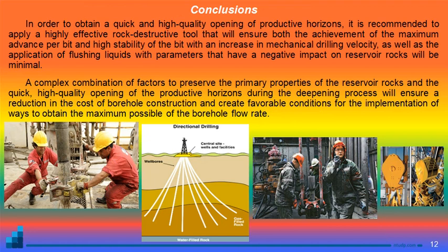In order to obtain a quick and high-quality opening of productive horizons, it is recommended to apply a highly effective rock-destructive tool that will ensure both the achievement of the maximum advance per bit and high stability of the bit with an increase in mechanical drilling velocity, as well as the application of flushing liquids with parameters that have a negative impact on reservoir rocks will be minimal. If proper conditions for opening productive horizons are provided, the coefficient of recovery of the permeability of productive horizons can range from about 40 to 90%.